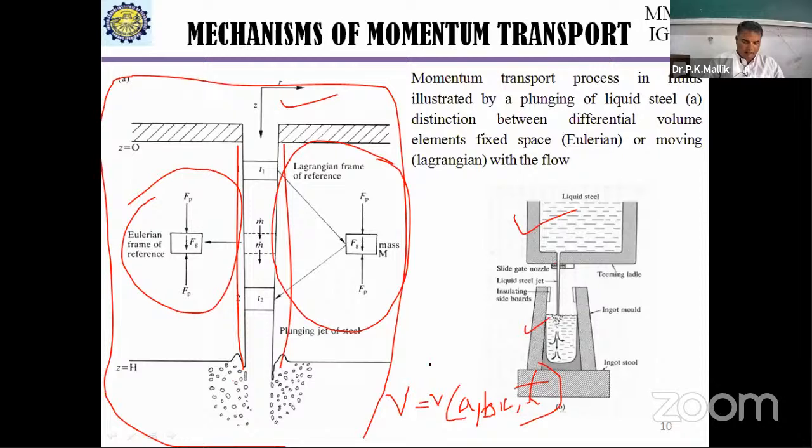It gives the value of a particular fluid variable at a fixed point in the flow, rather than the value of a fluid variable experienced by an element of fluid along its trajectory. So the Eulerian approach gives the value of a fluid variable at a given point and at a given time.